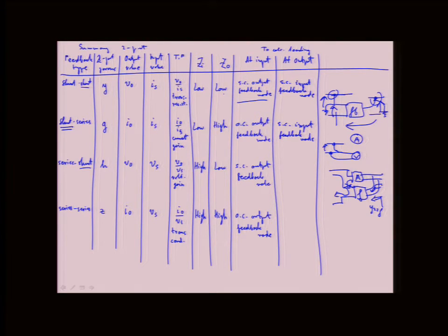In the shunt case, it had something that looked like this: Y21F times the current, I in, and then Y22F. So the only way for me to kill this is to basically disable this source. Then I'm really seeing just what this impedance is.